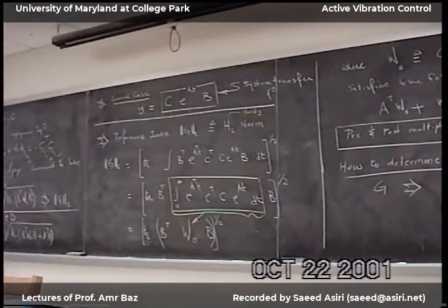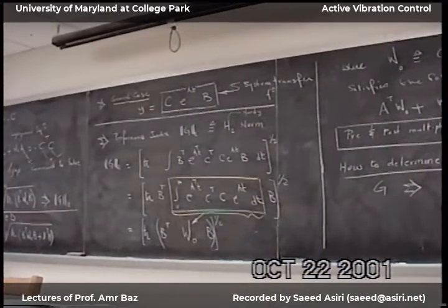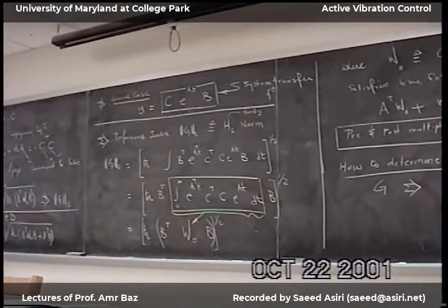So we can put all these bounds, and I can put these bounds in the time domain or in the frequency domain. So we put all this, and the final form will look like an LQG controller, exactly like what we have. And it reduces to two Riccati equations, one for the controller and one for the filter.